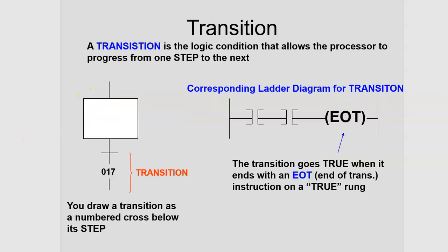This says a little bit more about the transition. I mentioned that if you clicked on this, then you can put code in there. So whatever, these are checking something. Maybe they're checking the presence or absence of something. But if these are true, and it's okay to transition out of this step, then it'll go to the next step. So the transition and the step are used together.